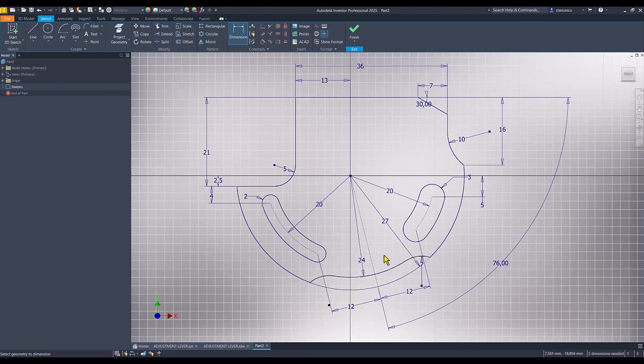I make symmetrical this by using coincident, not that construction, but coincident between the midpoint of this arc and this line. And now I place 16 between this end and this end of the major arc. This is 16, my friends.